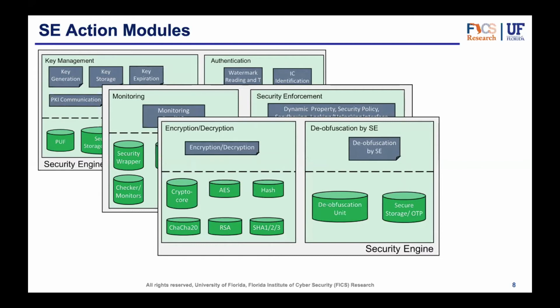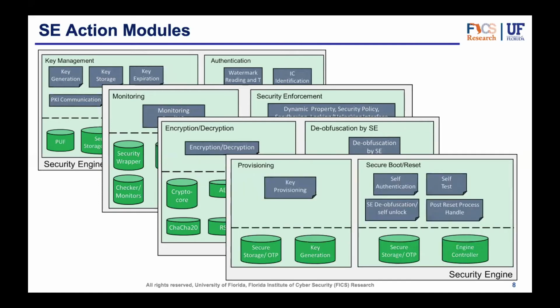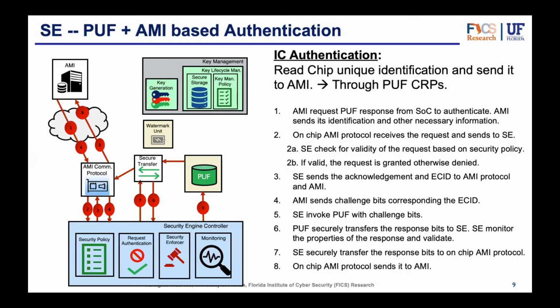Encryption and decryption, AES, DES, hash, RSA, quite a few security IPs that are planned to be developed. The obfuscation is also done by the SE, the security engine, and that does require key management. There's a number of IPs that are obfuscated, so the key has to be managed, but also the obfuscation during secure boot is managed by the security engine. Provisioning, as well as self-authentication, self-test, mentioned by Brandon again, and so on and so forth. So there are these additional functionalities and IPs.